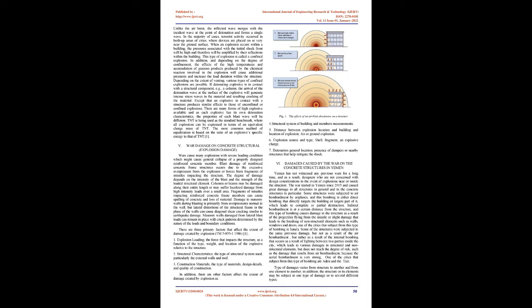4. Forms of explosions on the buildings. Unconfined explosions can occur as an airburst or a surface burst. In an airburst explosion, the detonation of the high explosive occurs above the ground level and intermediate amplification of the wave caused by ground reflections occurs prior to the arrival of the initial blast wave at a building as the shock wave. The pressures of air blast shock wave exerts on a structure's surfaces may be orders of magnitude greater than the stresses that structure has been designed to sustain. The shock wave may also act in directions that the building has not been designed to resist.